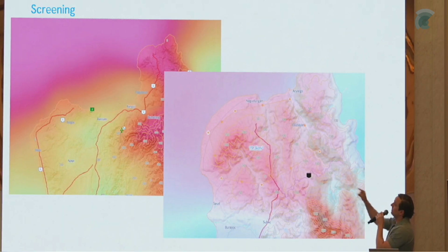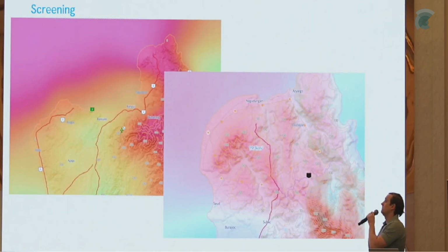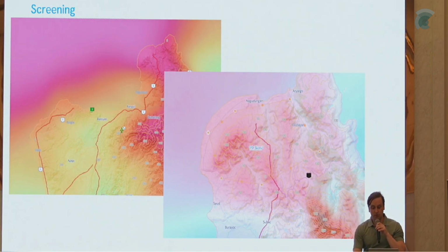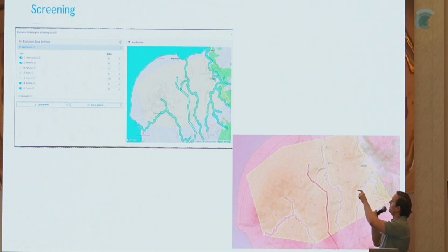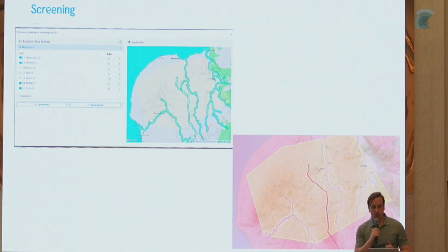And we can also add here a layer, which is restrictions to the layout design, which are, for example, grid connection. You don't want to build too heavy of a grid connection. You want to stay relatively close to those. Where are the roads, and where is there a harbor, to have the turbines fit my logistics center. So what we do here in the first part is basically the screening. You can simply draw a very big polygon on where the area is, where the wind speed is the highest, and you can filter out on different items.